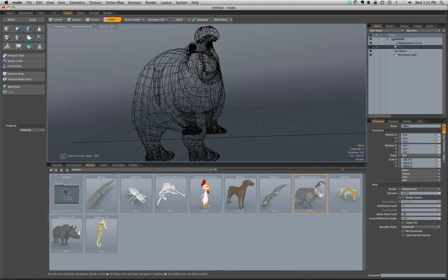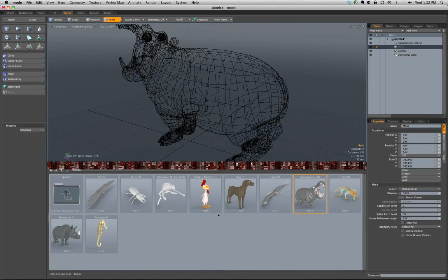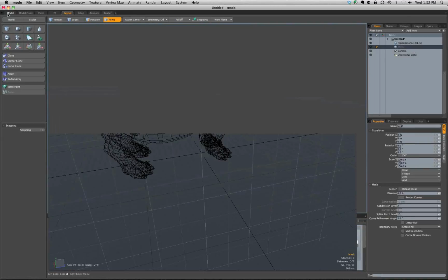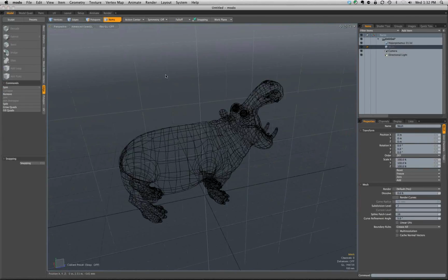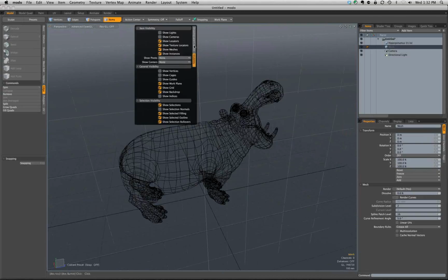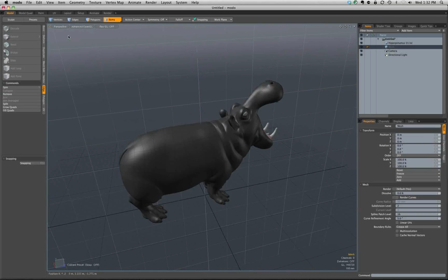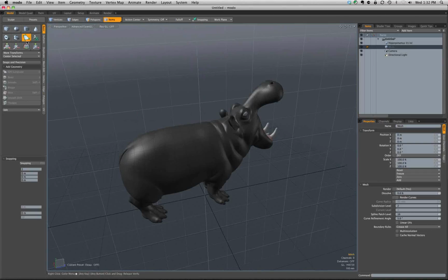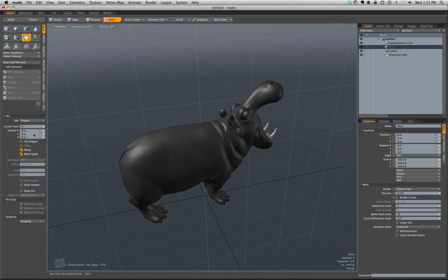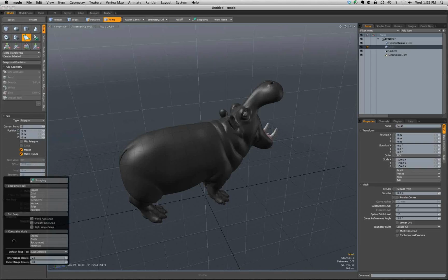Okay, so a number of things, and this is related to snapping. I'm going to press the O command, and let's get our visibility set the same so you can see it. If I've got my patch tool here, and I want to make quads, down under snapping, if I open this up, this has been enhanced quite a bit.